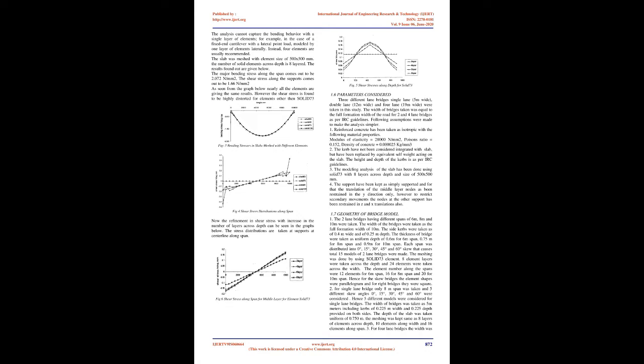1.4 Type of element used. SOLID 73 is used for the three-dimensional modeling of solid structures. The element is defined by 8 nodes having 6 degrees of freedom at each node, translations in the nodal x, y, and z directions and rotations about the nodal x, y, and z axes.